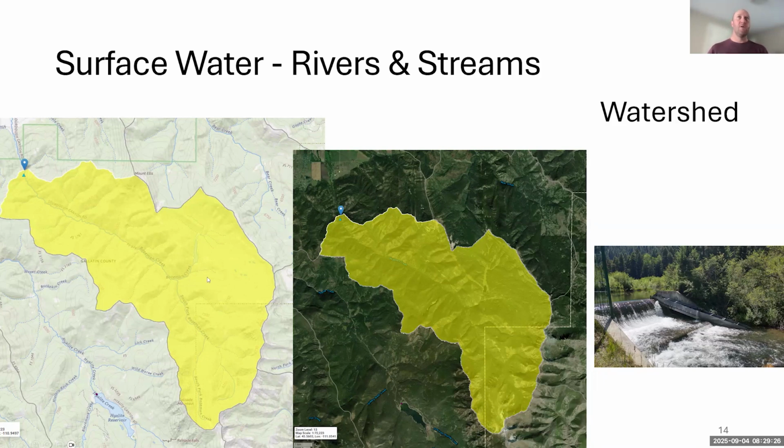And so because water always flows downhill because of gravity, and this is a pretty mountainous region, you can delineate all the water that, if it falls onto the earth, is going to eventually flow because of gravity down to a certain point. So in this yellow area here, which is the same thing as here, just with a different background, this is the topographic map, so you can see these topo lines, the elevation, and this is just the satellite imagery.